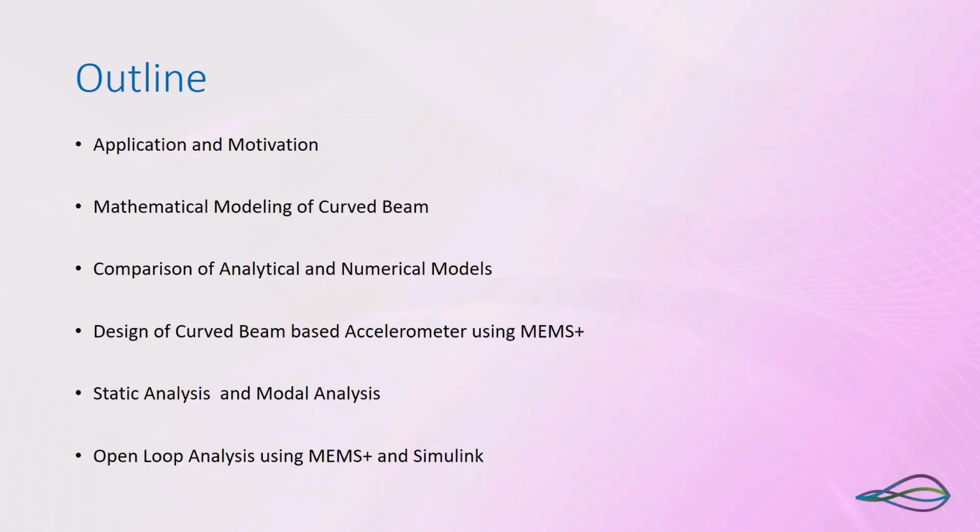So we have first done that modeling and then compared it with simulation from COMSOL. After that, we have utilized the curved beam in designing our accelerometer, which is an in-plane accelerometer. Then we have performed static and modal analysis, and afterwards closed loop analysis for converting displacement to voltage using MEMS+ and this Simulink model.